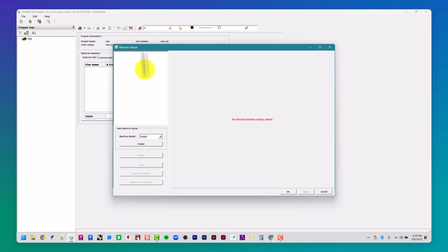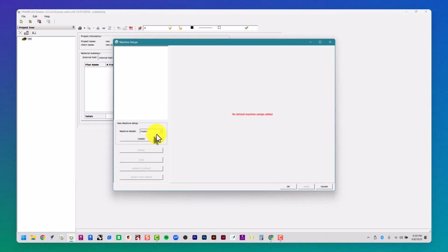And to get started, I want to choose the correct machine. The machine that we have here at Orange Coast College is the F325IT. It is meant for producing sticks that are 3 5/8 by 1 5/8, basically a 2x4. Now that's the only size section that it can produce. So F325IT, I'm going to click on Create, and now I'm going to walk through this process.